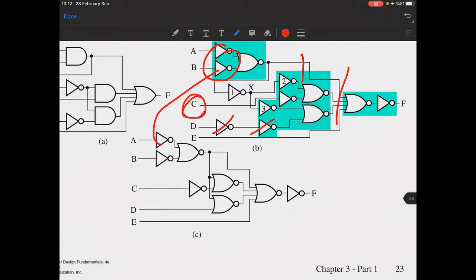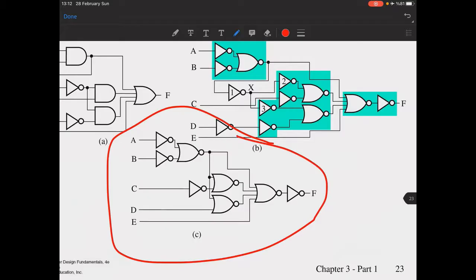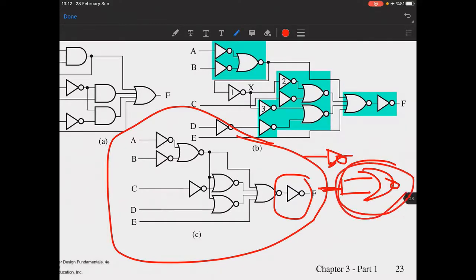Okay, so we will keep these basic input inverters here, right? And we will keep the inverter of C here, right here, and we will keep the inverter at the output here, like this. So in the end, your resultant circuit will be this one, and it is mapped to NOR. Again, if you want to convert the inverters as well, the inverter will be a NOR gate with the same input, right? So it can also be converted to an OR gate as well.